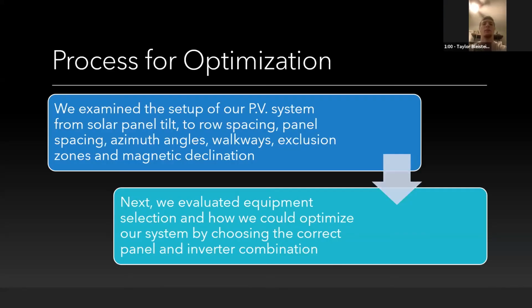Okay, so for the process of optimization, we really just wanted to examine basically everything in our system. We wanted to look at what panels we were using, how they're oriented, tilt, spacing, inverter selection. We wanted to look at our whole system, evaluate it, and think about what we could do better.